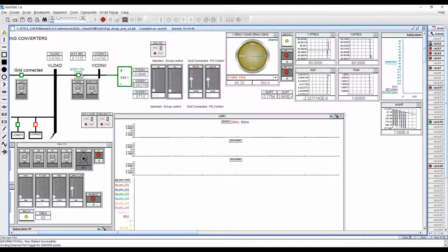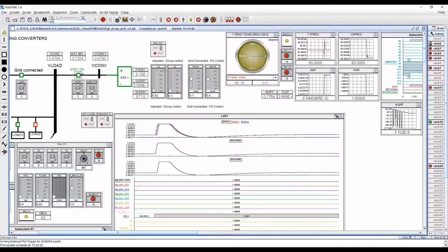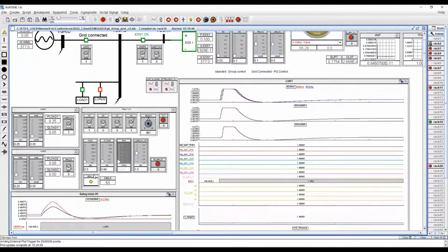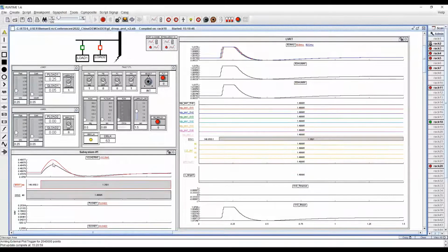The DR breaker is closed at 0 slip as expected. During the transition period, the step change in the RMS voltage at the PCC bus is below 5% of nominal voltage, which satisfies the requirement.